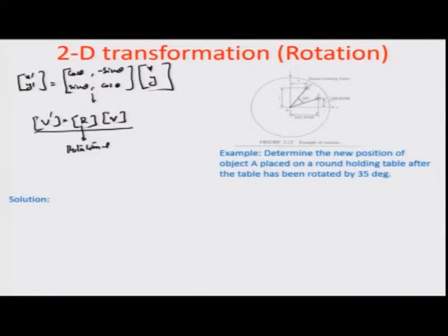So, let us do some problem example in this rotational transformation in 2D. Let us say we have a point A in space, which is given by the location coordinates 347.3792 x coordinate and 149.0298 y coordinate, and we are rotating this point A to a point A dash by an angle 35 degrees, and we want to find out what are the new coordinates just using this transformation equation that we have formulated